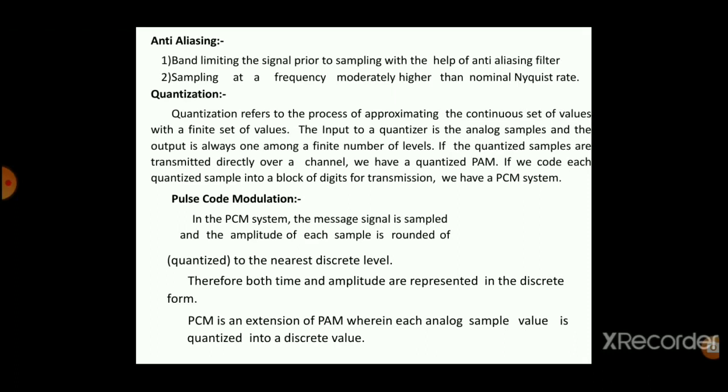Quantization. Quantization refers to the process of approximating a continuous set of values with a finite set of values. The input to a quantizer is the analog samples and the output is also one among a finite number of levels. If the quantized samples are transmitted directly over a channel, we have a quantized PAM. If we code each quantizer sample into a block of digits for transmission, we have PCM, pulse code modulation.